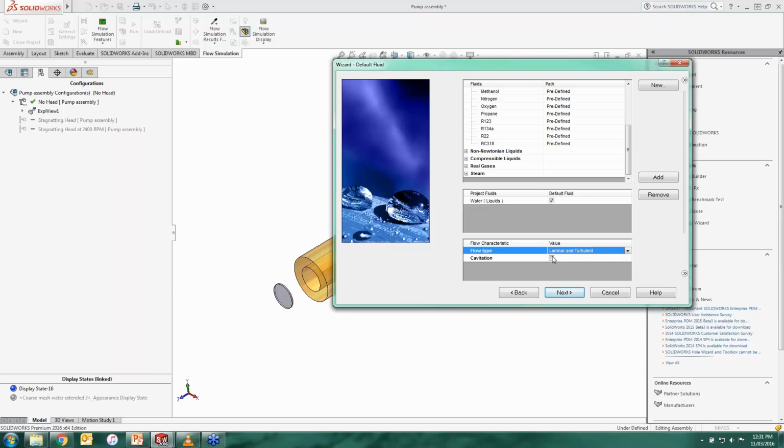One very important pause I would like to put here, in SolidWorks Flow Simulation, changing phase or multiple phase is not something we can cover. However, based on the density change of the fluid flow, we can decide it might have a cavitation occurred. So this is another topic and we might discuss it later on, but just letting you know, if you're in this, let's say, procedure of doing any turbomachinery design which considers that fact of the phase change, this is not the appropriate software. But if you don't have this effect, definitely you can add cavitation at this stage.